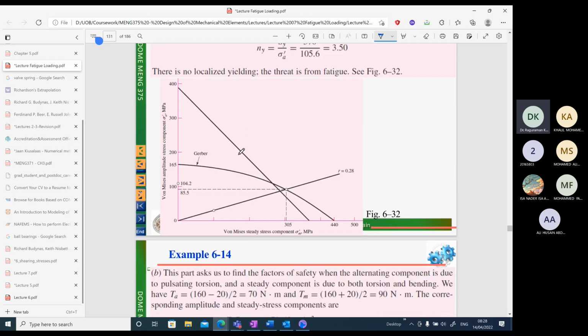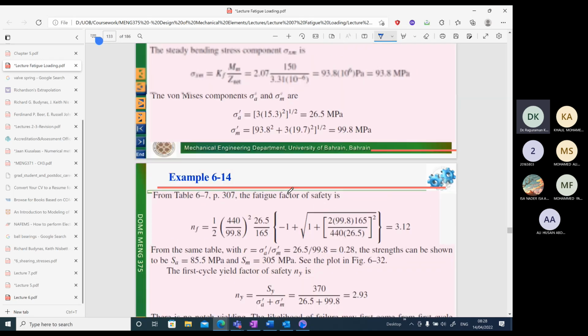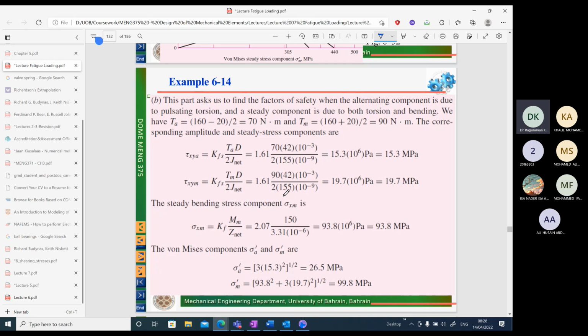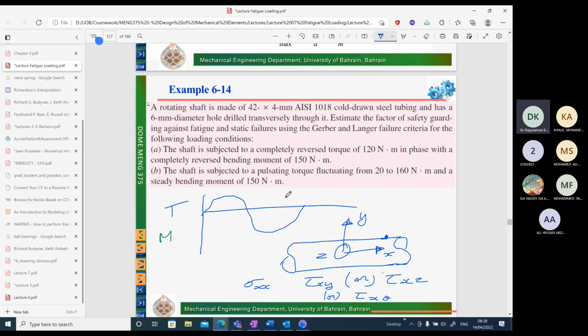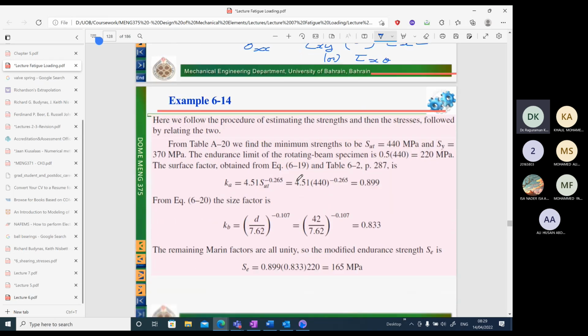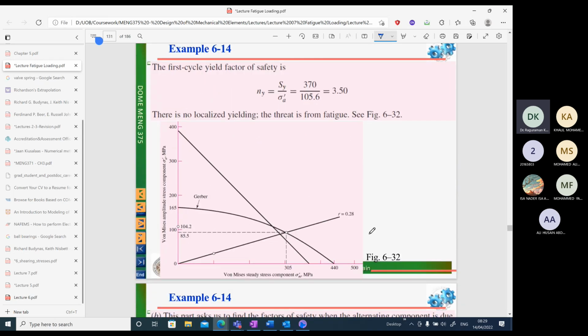So we are definitely in this region. This means we will get first fatigue failure as we increase the load along the radial load line, and then the yield failure. So there are different methods shown. In the previous problem, let's check it again. Both by Gerber method. Okay, so this is the result we have.